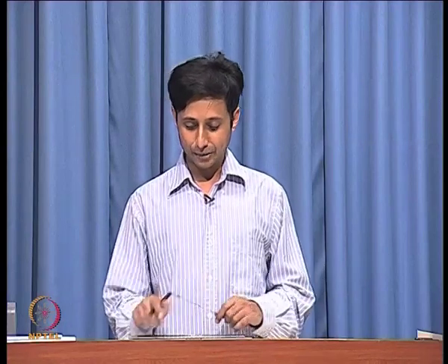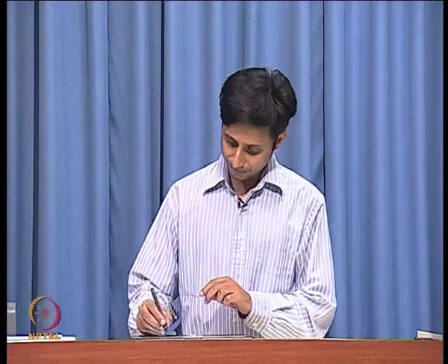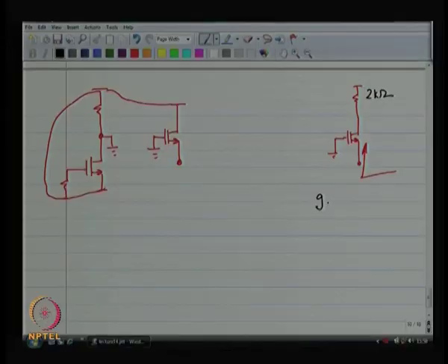All right. Now, I just have this, and if you go back to your analog circuits, the impedance looking into the source, when you have got the drain connected through a resistor to ground, gate is also connected to ground. This comes from a template. It basically looks like this: RDS plus RD divided by 1 plus GM RDS, right.